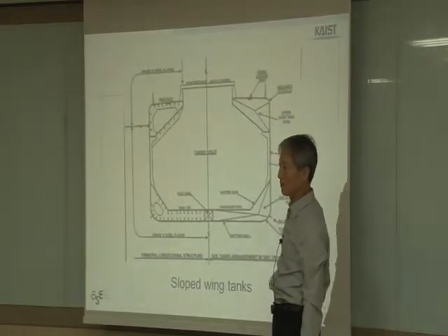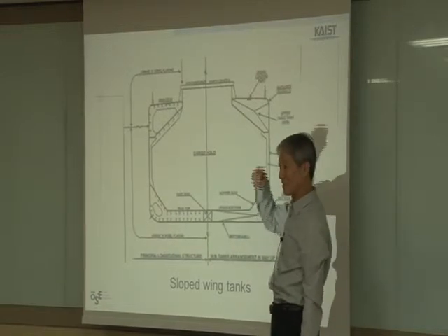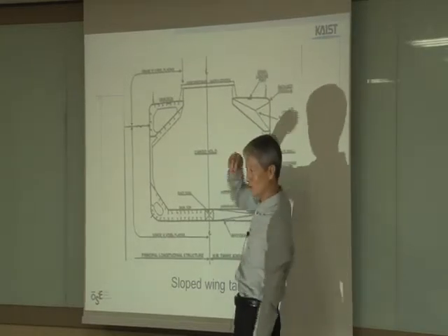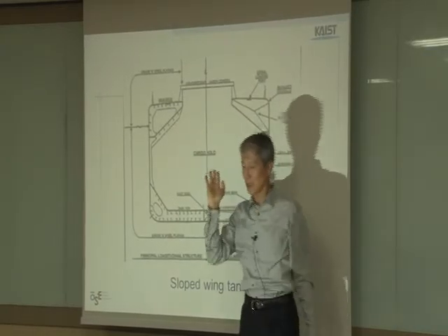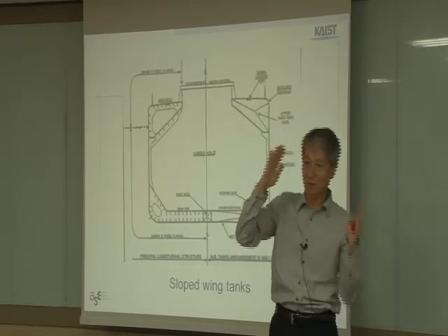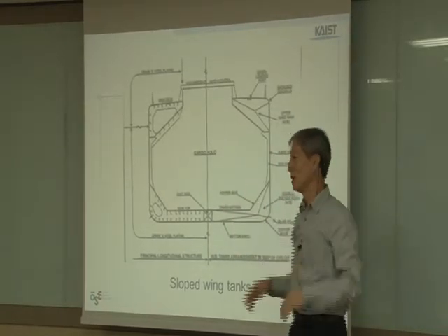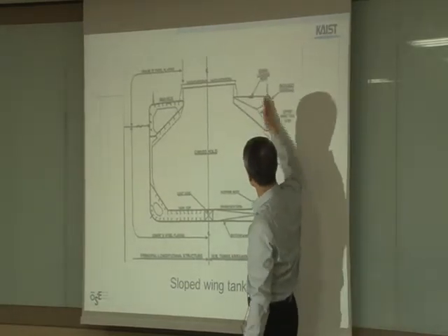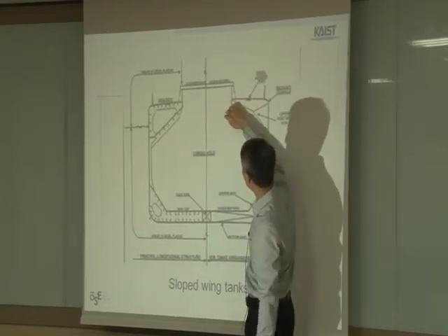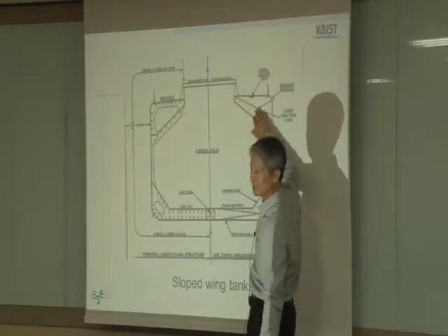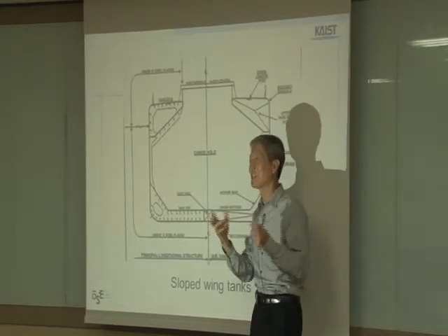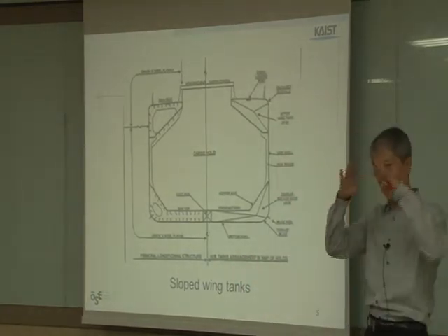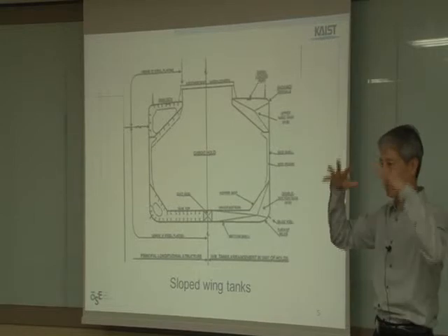What is the purpose of the slope? Why the purpose? It's a grain, right? Grain is pouring, so the shape usually comes in this way. Also, when the ship is rolling, the shape goes this way. The most important thing is that with this shape, it is very hard to fill up this corner. Shaking is easier, right? So that's a natural way to keep that space filled up.